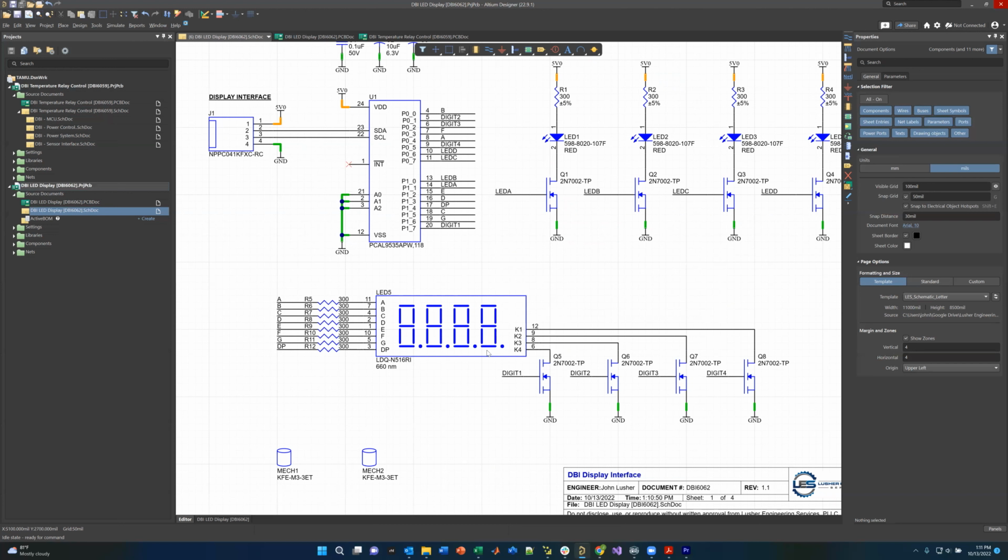If I wanted 8 and all the decimal points, I would put all these as highs. I'd put basically 5 volts on all of these, and then turn on all these cathodes, and then the entire thing would light up. But obviously, if I want 0001, I would have to light up all the different ones, and then set each digit, and then set only the first two to be the right hand side here of these digits.